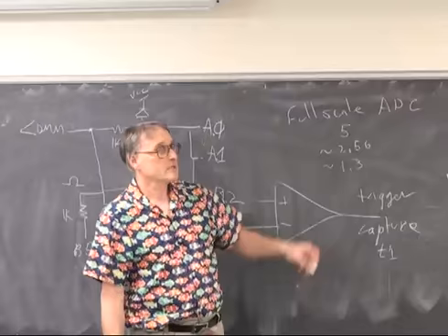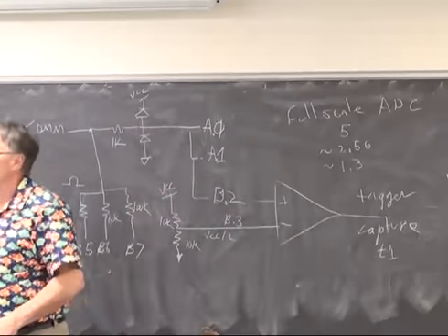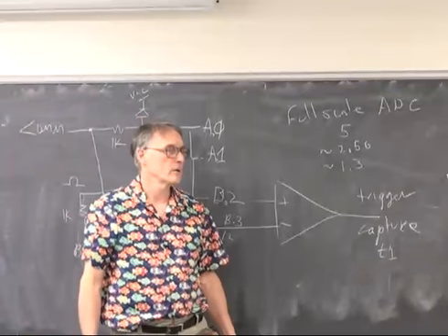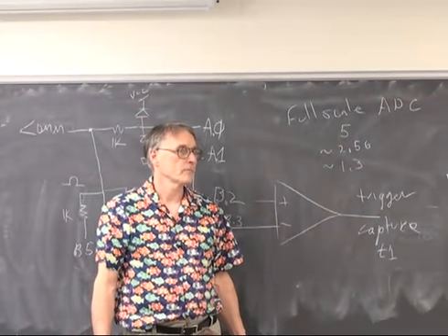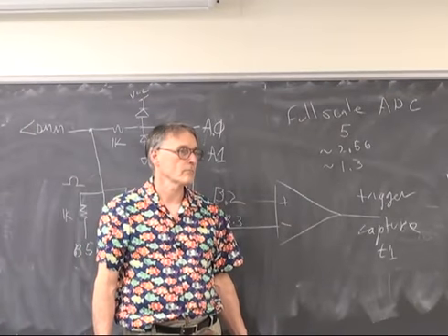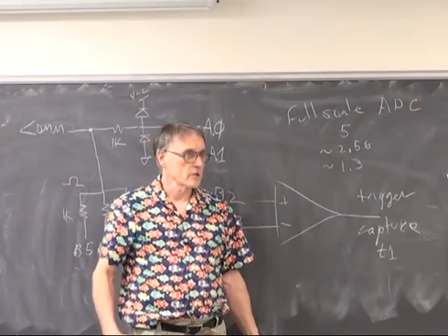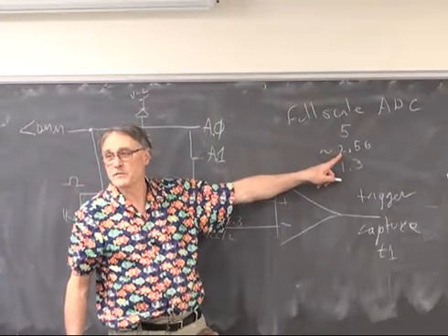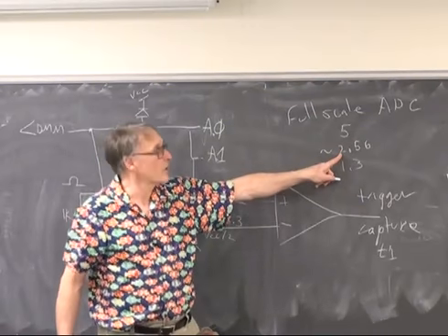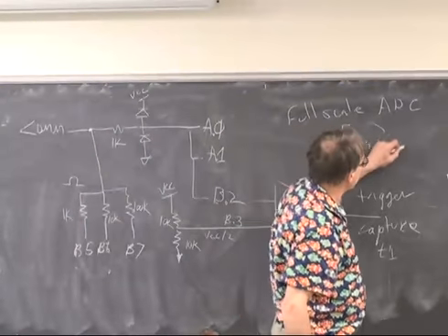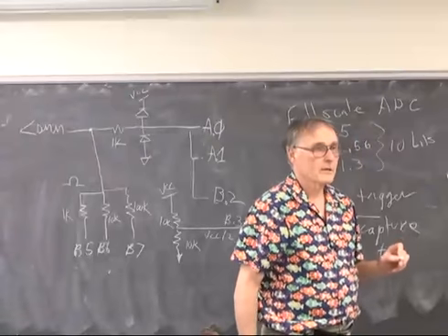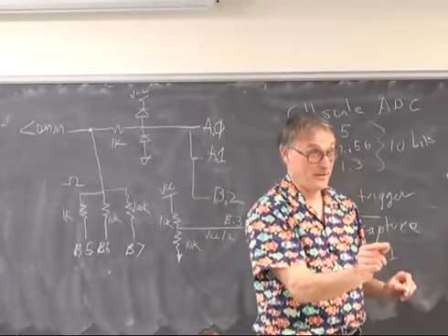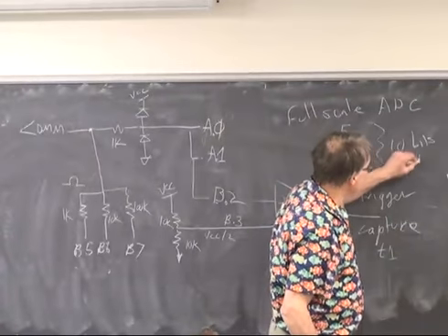So what's the procedure? How would you auto-scale, rationally auto-scale this? Jeremy? If you start it so it's always at 5 and then just check what the voltage is, and if it's less than 2.56, then you can change the scaler and remeasure it? Yeah, that's right. So you'll step down. If you get less than 2.56, you're going to get better accuracy if you change full scale to 2.56. Because in all cases here, you get about 10 bits out, if you're really, really obsessive. If you're not really obsessive, you get 8 bits.